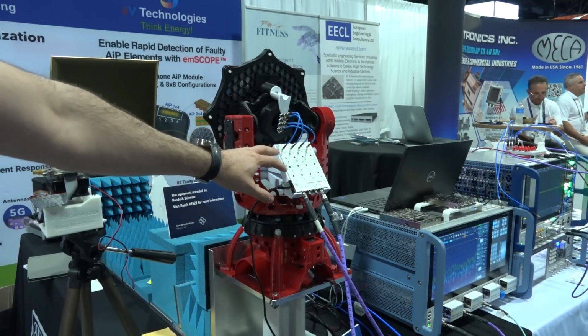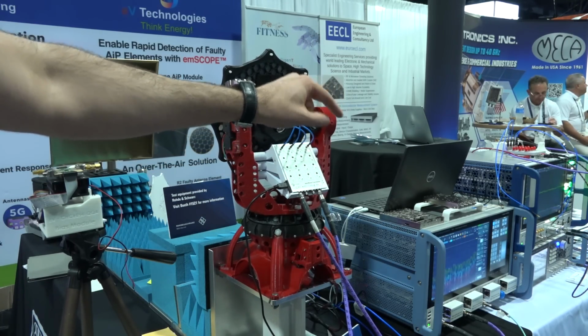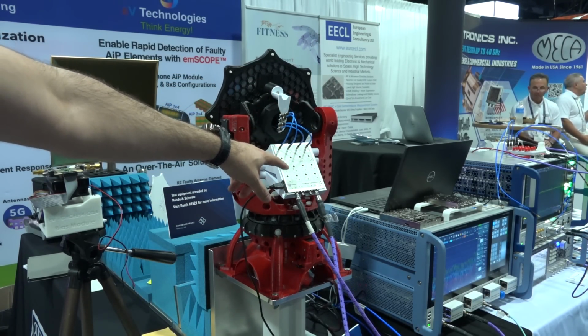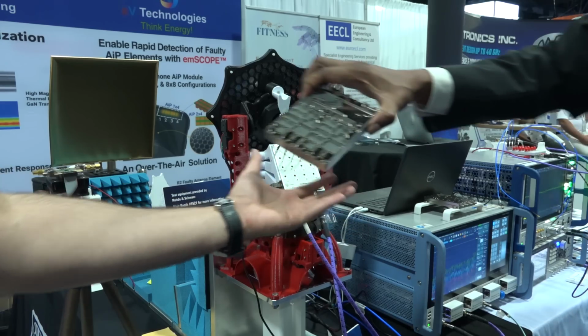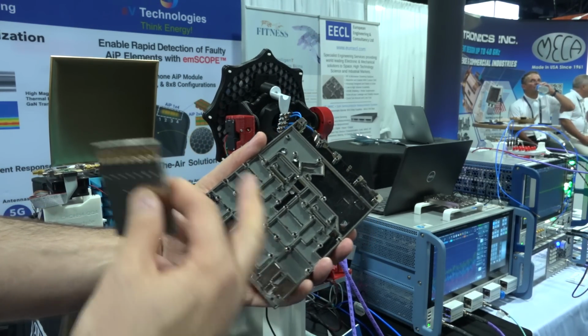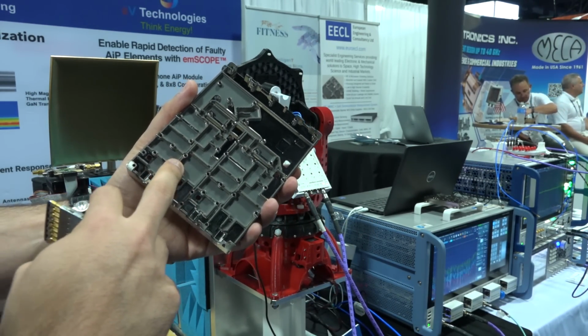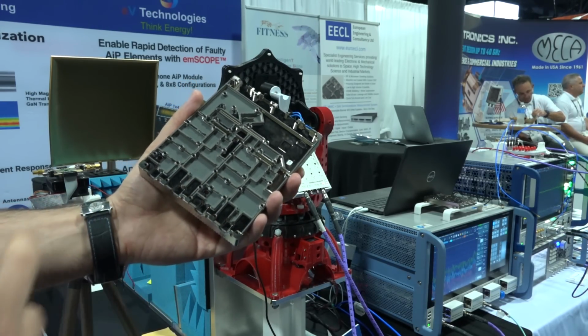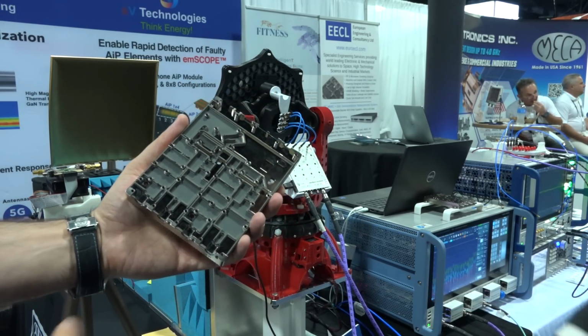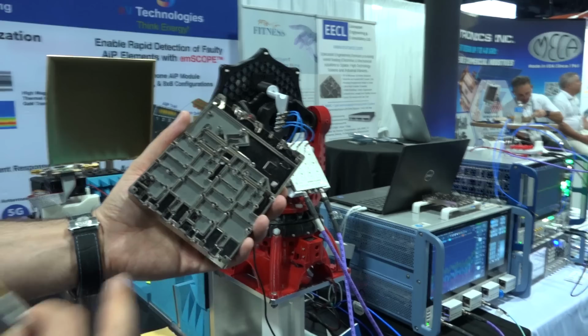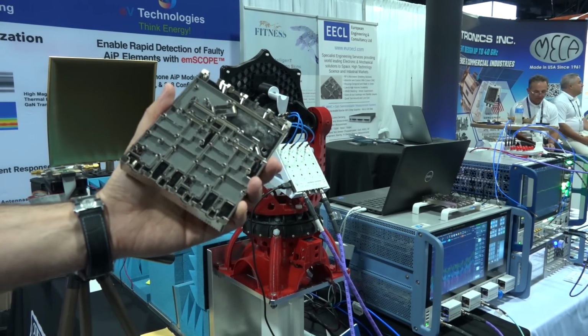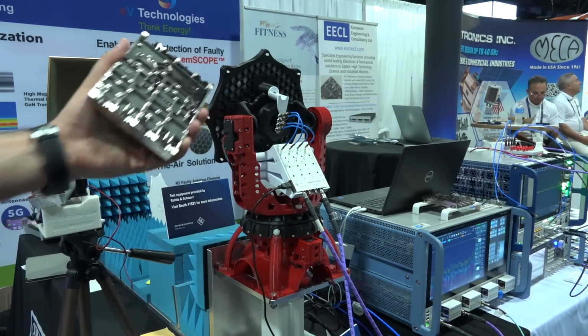The isolation, 100 dB in these modules, is accomplished via a very specific gasketing technique they have in their devices. You can actually take a look at it here. There it is, and that allows you to get this 100 dB isolation. It almost looks like it's printed or deposited. This is gasketing developed by EECL, our partner. Right, UK. Yeah, it's developed in the United Kingdom, and that gives you this extraordinarily high isolation. So all these technologies come together in this setup.